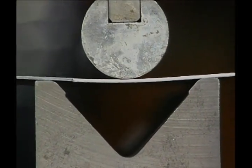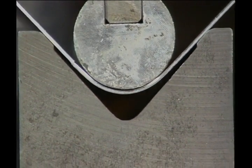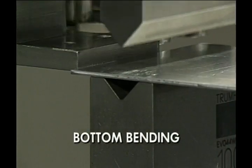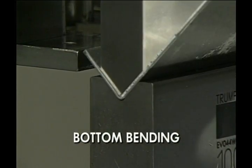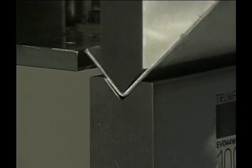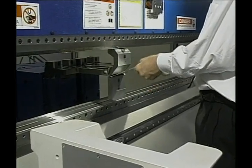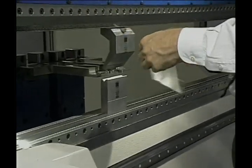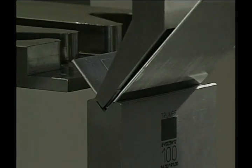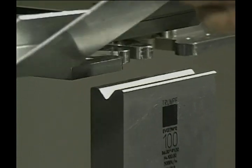Spring back is a particular problem in air bending. Allowance for spring back is made by overbending and then permitting the workpiece to spring back to the desired angle. Bottom bending forms bends by letting the punch force the workpiece against the lower die. In general, bottom bending produces more consistently accurate parts than air bending. Bottom bending is usually used for applications requiring a high degree of accuracy and sharp corners. Because of the high tonnage requirement, bottom bending is generally limited to bending steel no thicker than 1/8 of an inch, or approximately 3 millimeters.